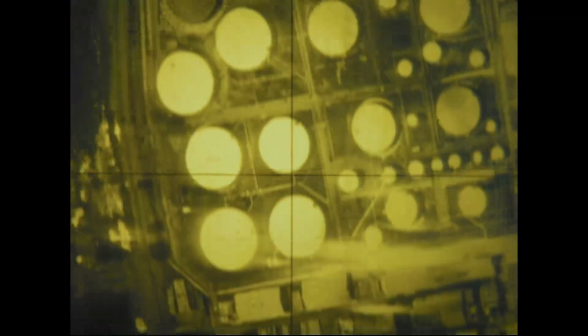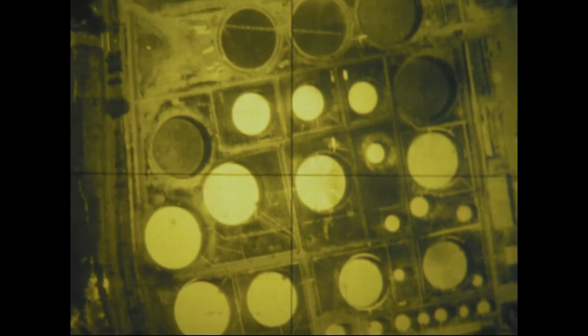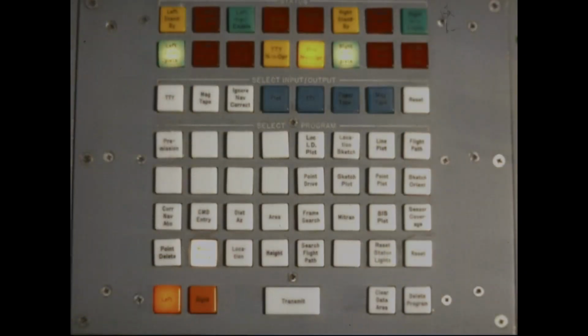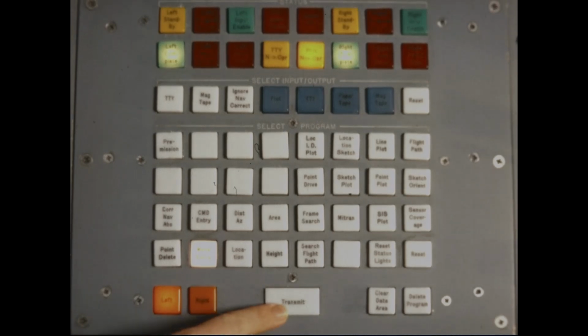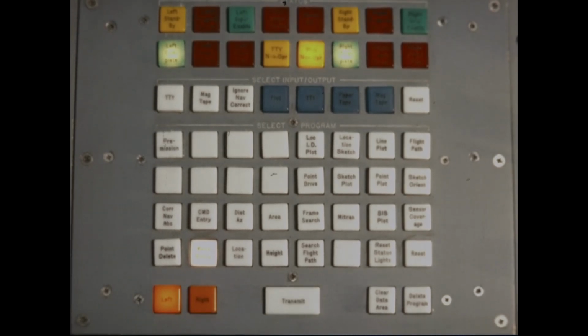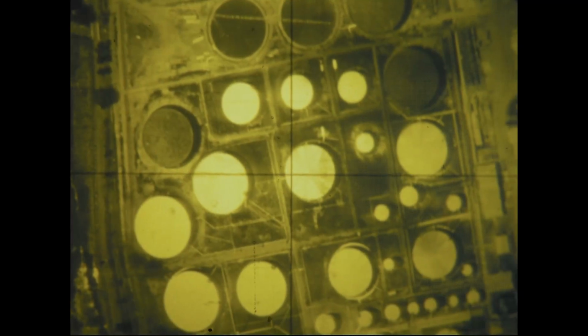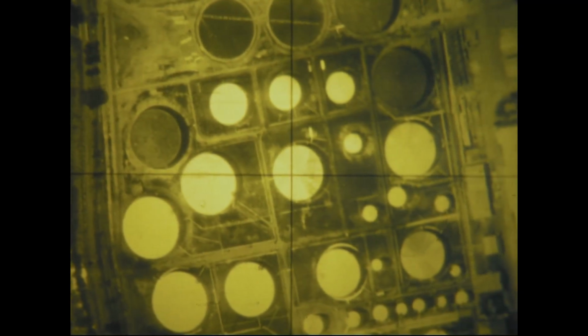The first point of interest is driven under the crosshairs. Let's say it's one side of an oil tank that we want to measure for diameter. The mensuration entry procedure is again used to store the coordinates for that point in the computer. The operation is repeated for the other side of the tank.